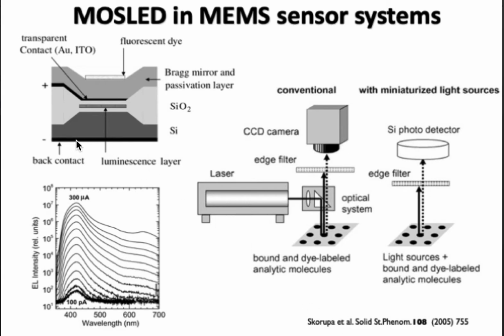Here you see a light emission device made in MOS technology with quantum dots coupled to rare earth ions for specific wavelength emissions. One can scan light sources electrically. It is made for mass-produced disposable quick diagnostic medical tests, while the traditional way is to use a tunable laser mechanically stepped over the surface.